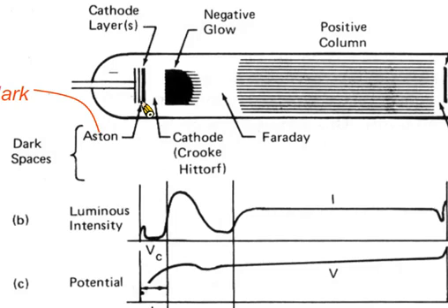Again, the negative potential drop here will accelerate the electrons. When the electrons come out from the cathode surface, they travel toward the anode, and when they travel across the cathode layer, they will gain very high energy. So these electrons are called primary electrons, with very high energy.